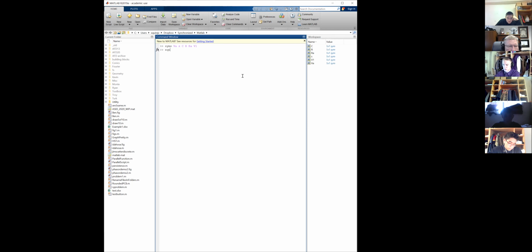Now let's create your equation. Maybe you have multiple equations, so I'll call it equation 1, and you put it inside a curly bracket. Then you just type your equation normally: VA minus 1 over S, all of that divided by R, plus VA times S times C. MATLAB doesn't understand implicit multiplication, so you have to say VA times S times C. When you're setting something equal to 0, you have to use two equals signs.